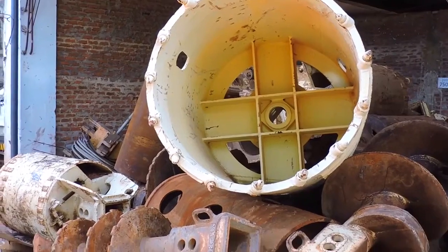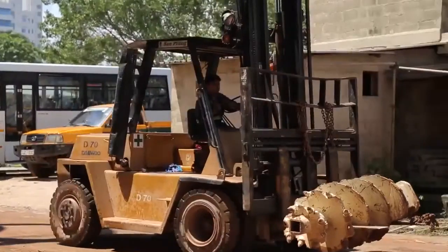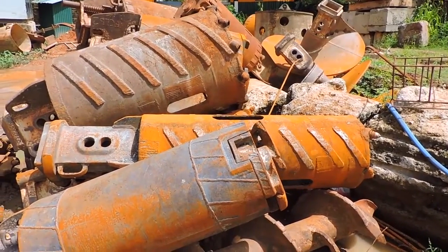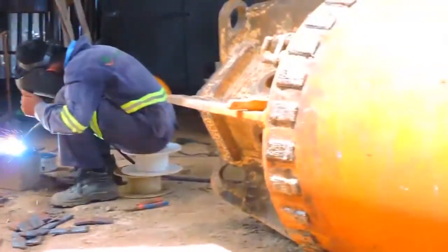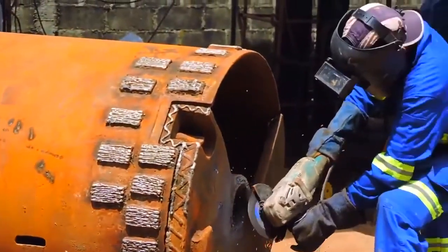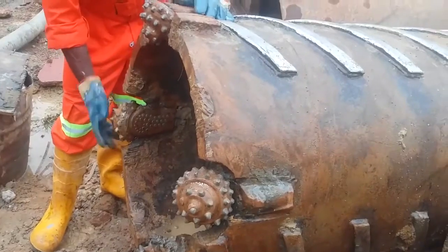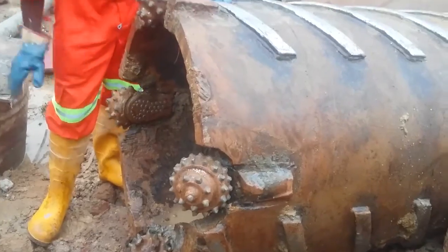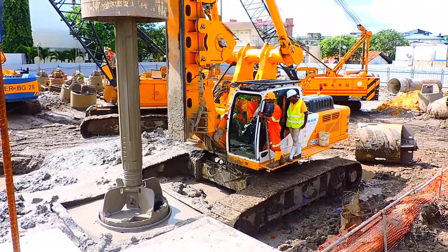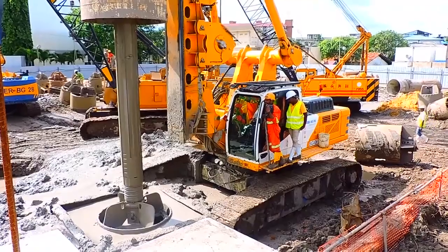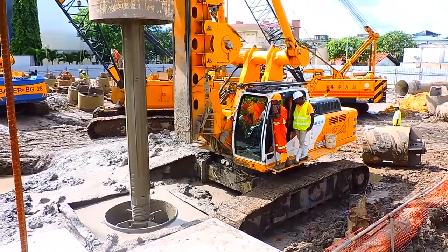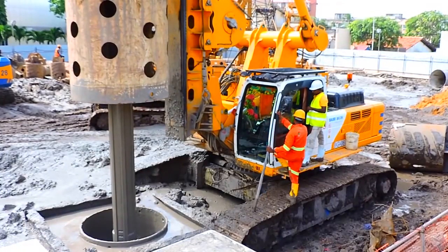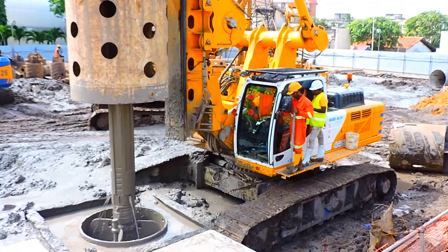The drilling process should be done using different tools according to the nature of ground layers. Soil auger and soil buckets are the tools that should be used in soil layers. Rock auger and rock buckets are the tools used in rock layers. For harder rock, core barrels with roller bits are used. In the drilling process, soil particles and rock particles in the drilling hole are collected into the bucket and removed from the drilling hole. After drilling, the pile bottom at the required depth is cleaned using a cleaning bucket.